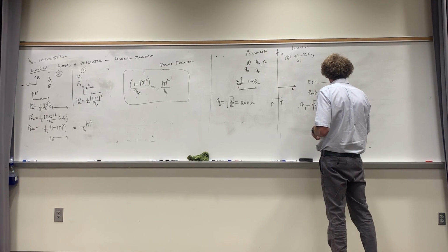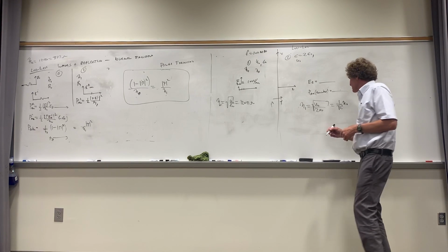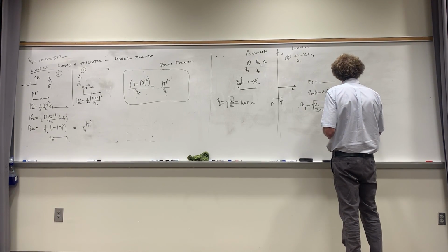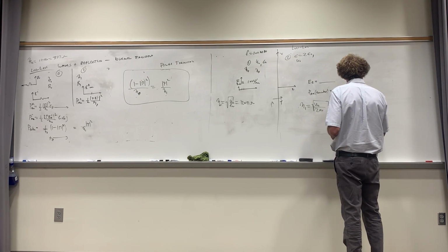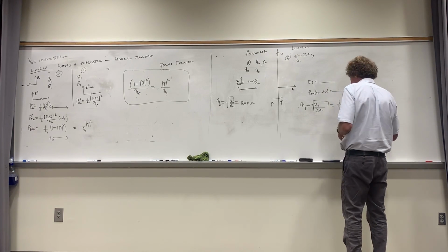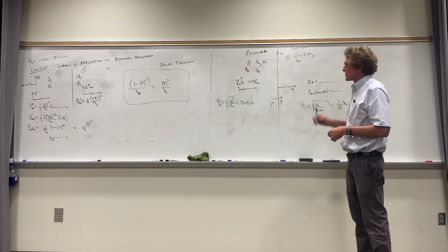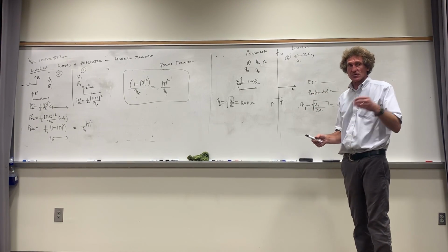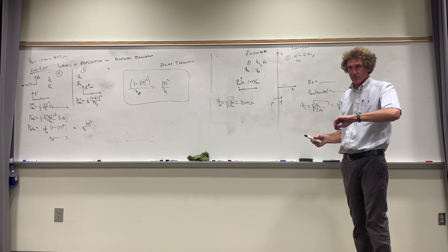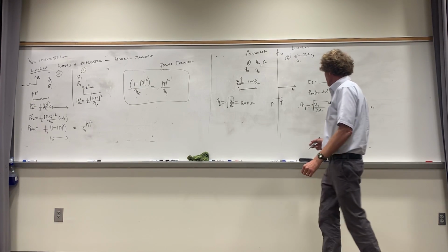It's 1 over the square root of 2 times that, isn't it, class? Or simply 120 pi divided by square root of 2, ohms. Correct, class? Now, since I'm looking for the transmitted power, I could use the transmission coefficient, couldn't I, guys? What's the transmission coefficient?